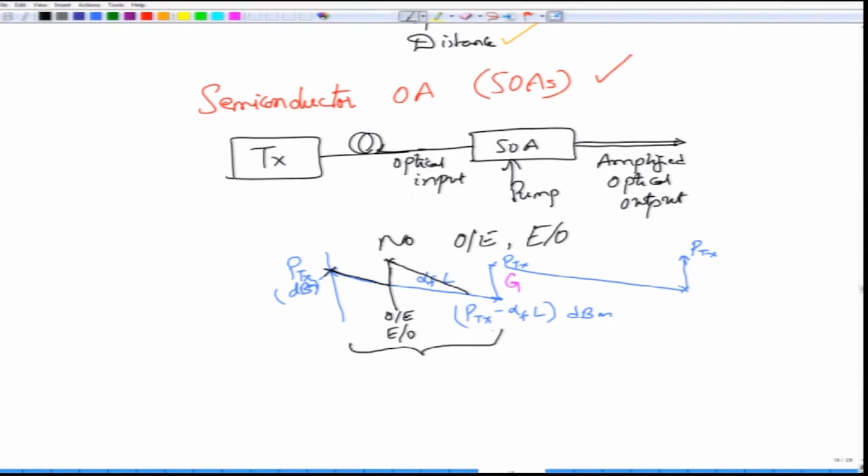This distance before you put in the first repeater or the first regenerator is called a span, or sometimes a repeater-less span. So, what would be the length of the fiber before you put in the first repeater? This is something where an optical amplifier would provide an advantage.